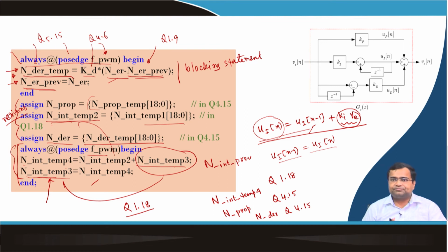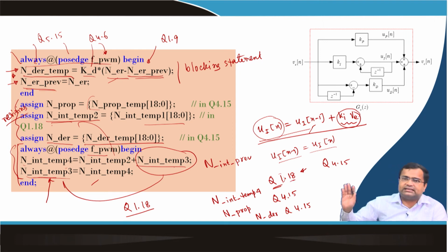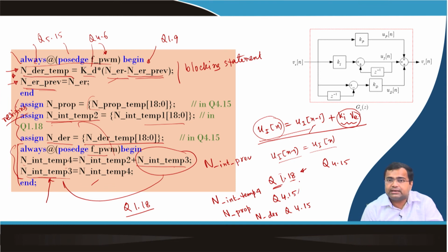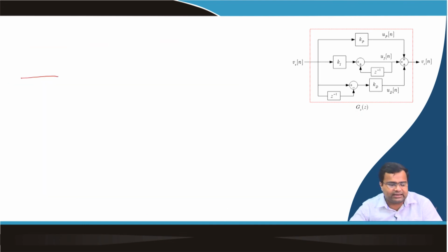So, we cannot add them. What do we have to do? First, this data we have to pad with a sign bit extension. That means we have to extend this sign bit 3 times, because we need to make it 4.15. Okay? And then we can discard 3 LSBs, because it is up to 18. Otherwise we cannot resize, or we can pad with 0. There is no point, so we can discard it. So, either you can discard this or you can resize. If you resize by adding another 3 zeros, the size will actually go up. So, it is a designer choice.